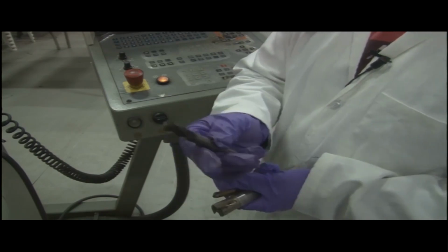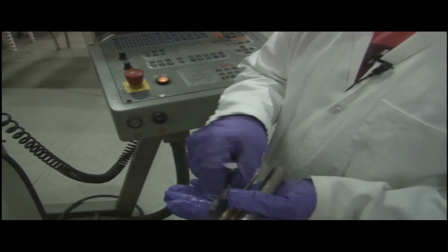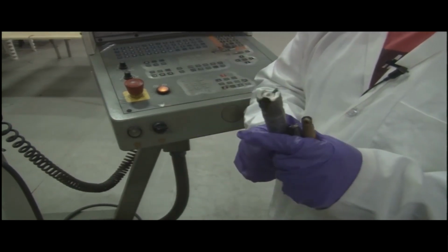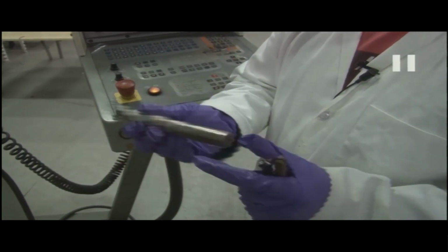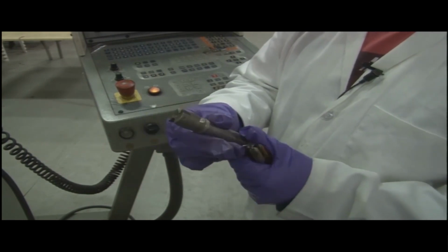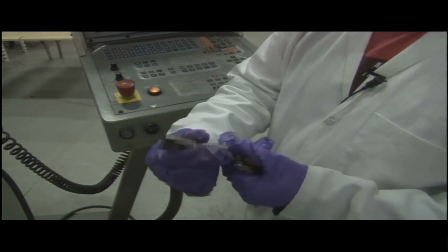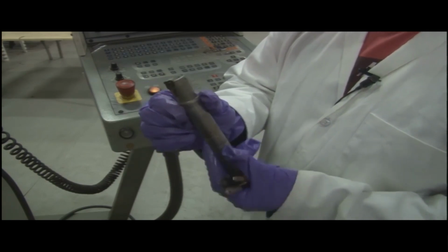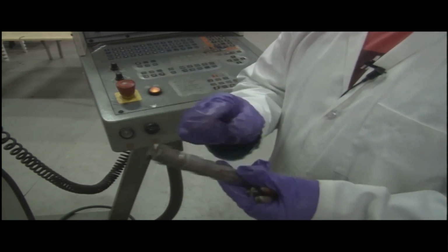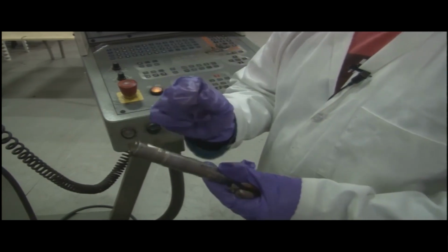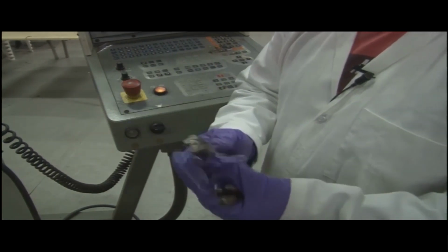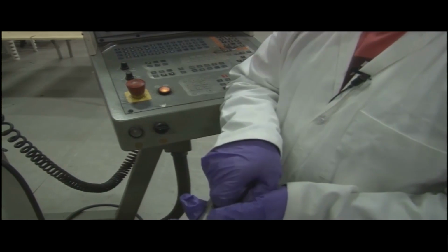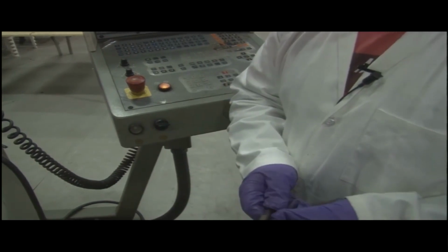This is a completely solid carbide tool. In the same way, we have this tool. This is an inserted tool. That was a completely solid carbide tool. It means that in this tool we have separate inserts. So, this is a tool in which the inserts can be put in, and they can be locked in using a screw. There is a sharp tip there, only the inserts get deteriorated and those can be changed. So, another kind of tool here is this.